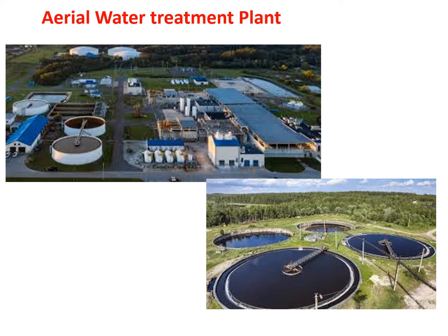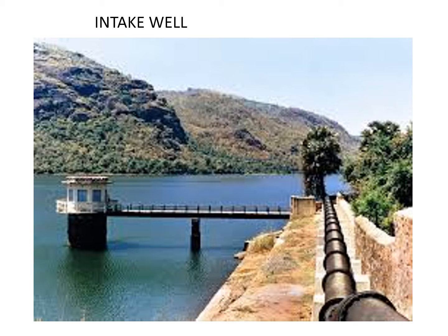This figure shows the aerial view of a typical water treatment plant. The unit that you can see here is a simple sedimentation tank. Here I will give a quick look at all the units that are generally included in a water treatment plant. This is the intake well, that is the collection system, constructed along with this footbridge, over which you can see the conduits or conveyance pipeline which will carry water to the water treatment plant.